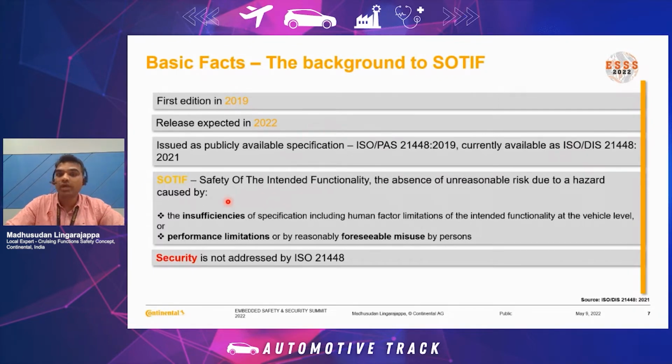SOTIF, according to ISO 21448, is defined as the absence of unreasonable risk due to hazards caused by any insufficiencies of specification, including human factor limitations of the intended functionality at the vehicle level, or any performance limitations, or by any reasonably foreseeable misuse by the persons. Finally, security is not addressed by ISO 21448.